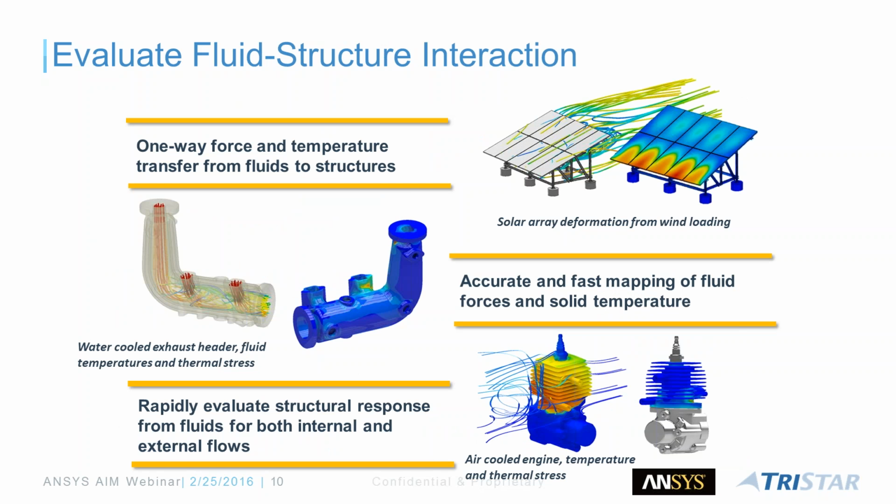And then the fluid structure interaction. You can see the example of the solar panel right there, where obviously I need to do a fluid flow analysis. At the same time, I want to couple the forces and the pressure that I get out of my fluid flow into a structural analysis and see the structural performance of the entire product or the assembly, right?